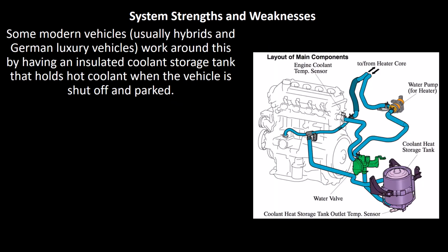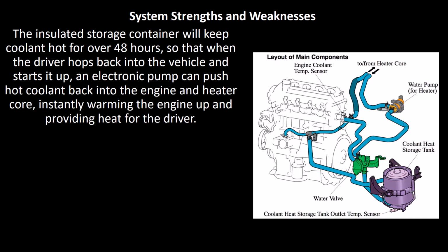Some modern vehicles, usually hybrids and German luxury vehicles, work around this by having an insulated coolant storage tank that holds hot coolant when the vehicle is shut off and parked. The insulated storage container will keep coolant hot for over 48 hours so that when the driver hops back into the vehicle and starts it up, an electronic pump can push hot coolant back into the engine and the heater core, instantly warming the engine up and providing heat for the driver.